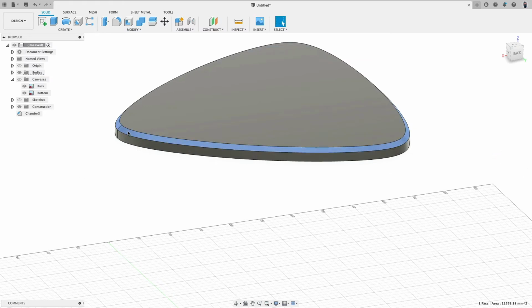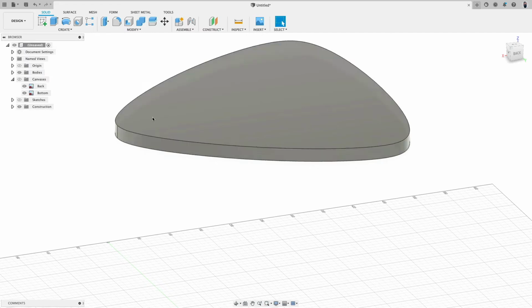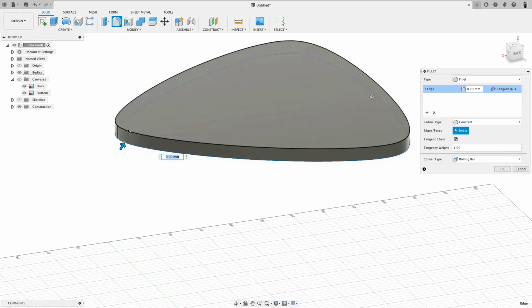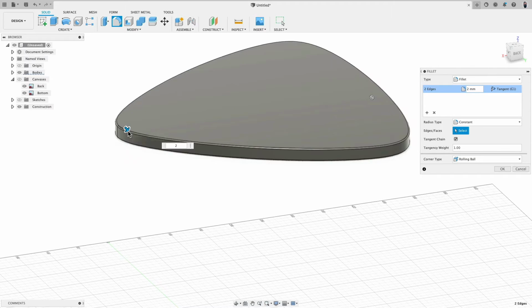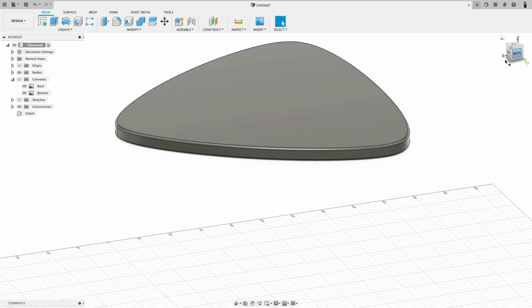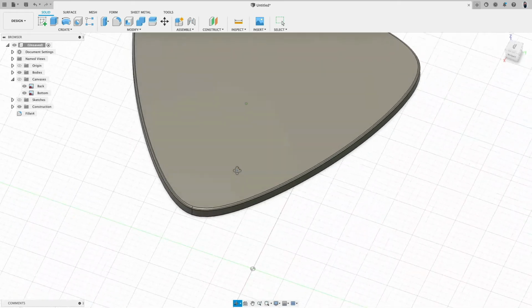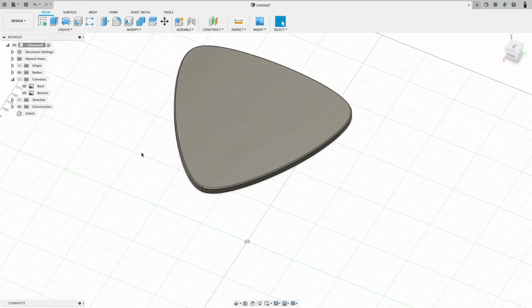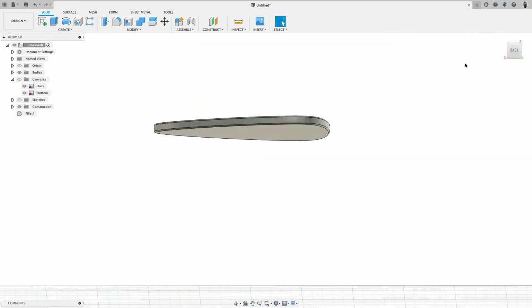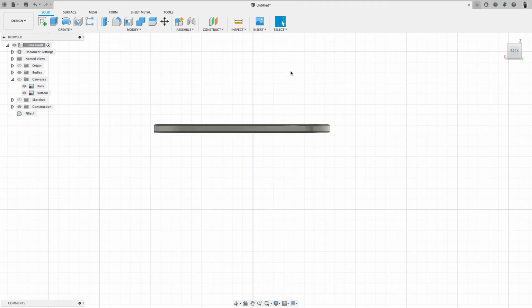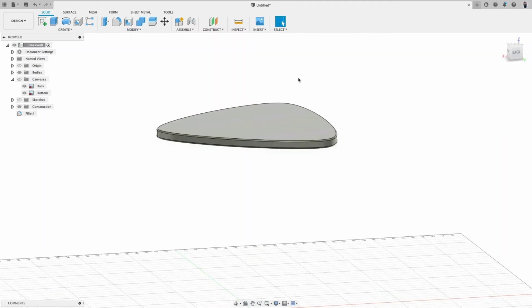Actually, I like it to be filleted. Okay, let's select the surface and delete it. Go fillet, click, click. 2 millimeter, 3 millimeter. That's good. Yeah. So you see actually how powerful this type of modeling is. You don't have to redo stuff necessarily. You just remove steps and then add other steps and you get your original geometry back. Very nice. So I would say at this point, we actually finished modeling the tabletop.